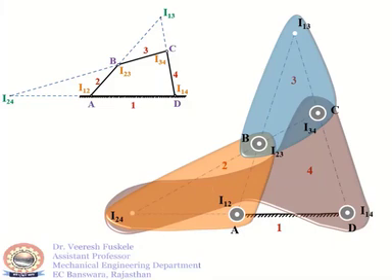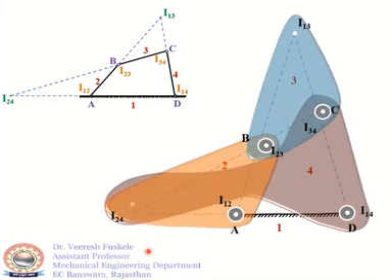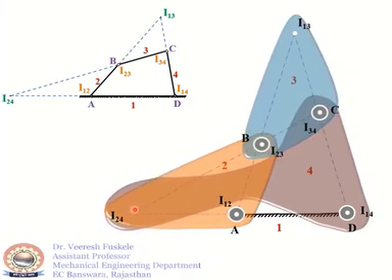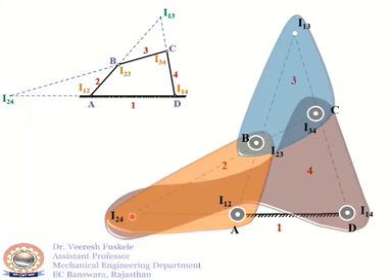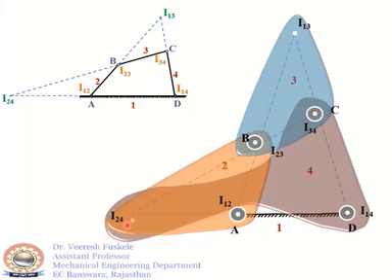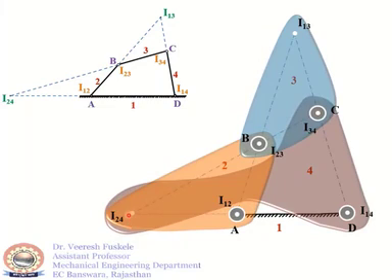Around this configuration, these 2 points move with the same velocity, as we can see here. You can't see 2 different points, there's only a single point, so they are moving with the same velocity. So this is how you can understand how I24 is lying on 2 and 4 and I13 is lying on 1 and 3.